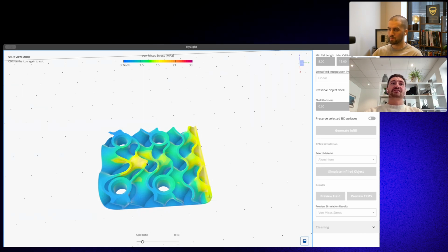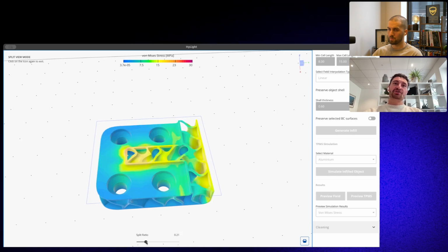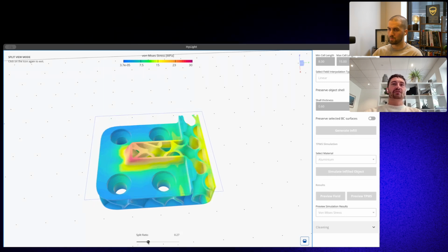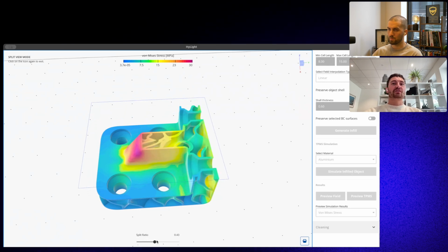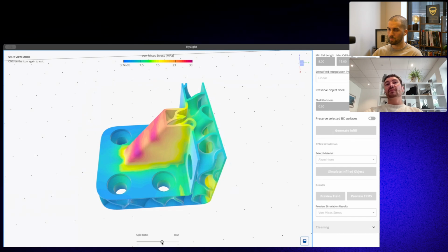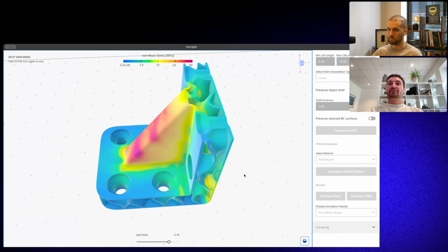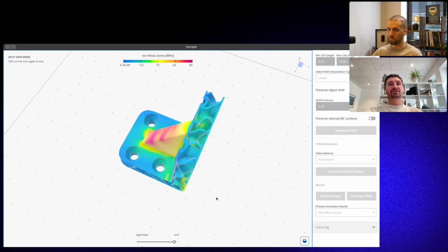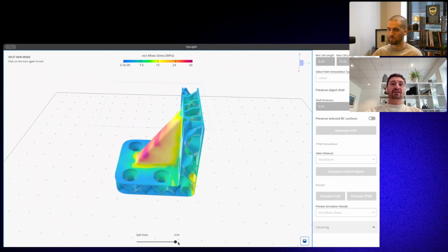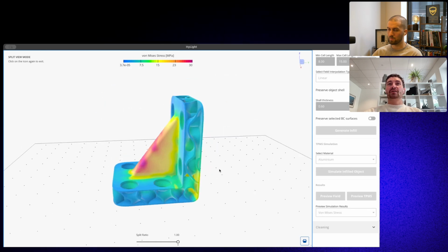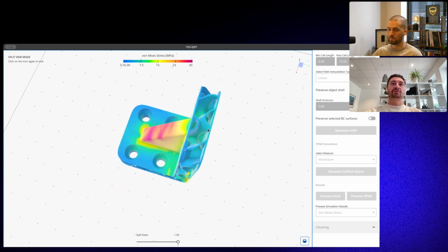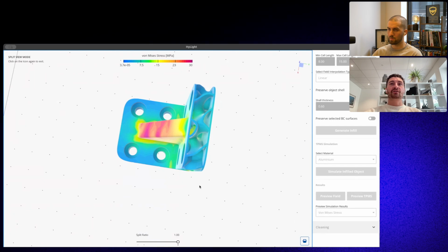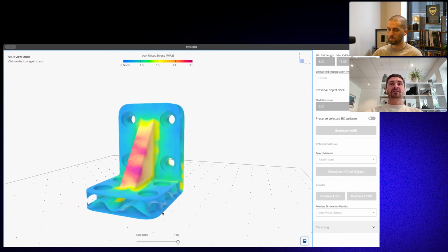You can see that the cell size of the respective gyroid unit cell is squished wherever there is high load, so high stress. You can see that the cells here turned much smaller in comparison to the remaining cells. This has interesting properties, of course, for all sorts of applications. First of all, it's making the structure much more lightweight, but it is also a nice structure to be depowdered, as long as there are no powder enclosures, which in this case did not happen.